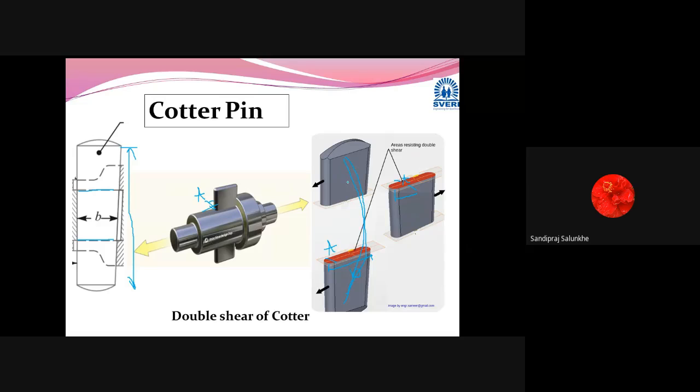It will get bent because this part, which is held by this socket pivot, and this upper part, which is held by this socket, this upper part is pulled with the socket to this side, and this inner part with this pivot is pulled to this side. This is the condition. So if it does not shear, then it is possible that it will get bent like this. Okay. So we have to calculate the bending stress.